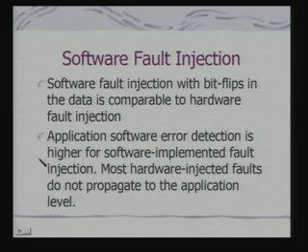So, one way of testing is what we have talked about: we have defined the testing schemes and the test patterns, and to see whether your system gives a desirable behavior, you inject faults into the system, because you cannot really expect the faults or bugs to come up on their own always. You see whether an injected fault is getting detected by your testing process or not, because you exactly know the fault that has been introduced, and then you can be sure that your testing process is correct and your implementation is possibly desirable.